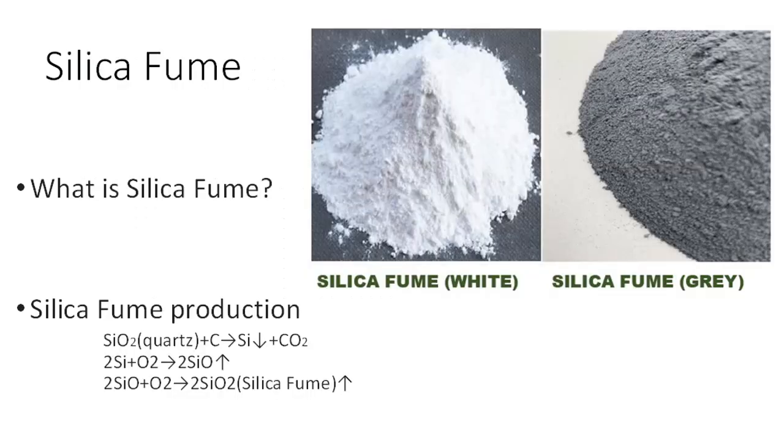Thanks to its high pozzolanic activity and fine particle size, silica fume significantly enhances the strength, durability, and workability of concrete, mortar, and grouts. It is commonly used as a supplementary cementitious material to improve the performance of concrete, especially in terms of compressive strength, bending, seepage resistance, and corrosion resistance.